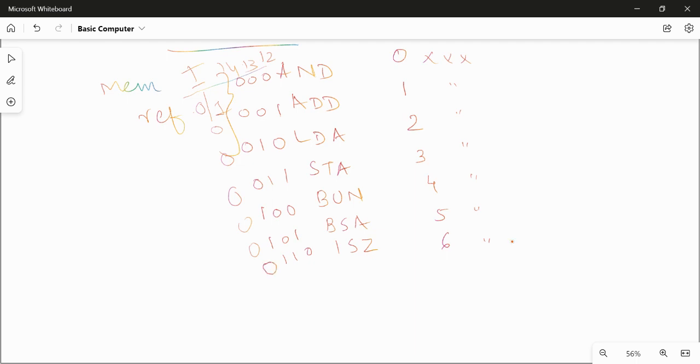Now if you convert these 4-bit binary values to hexadecimal, you'll end up with this. 4 zeros is 0 in hexadecimal. Then 0100 is 4 in hexadecimal, and likewise. And this XXX represents the actual address value for the first 12 bits because they cannot be predetermined.